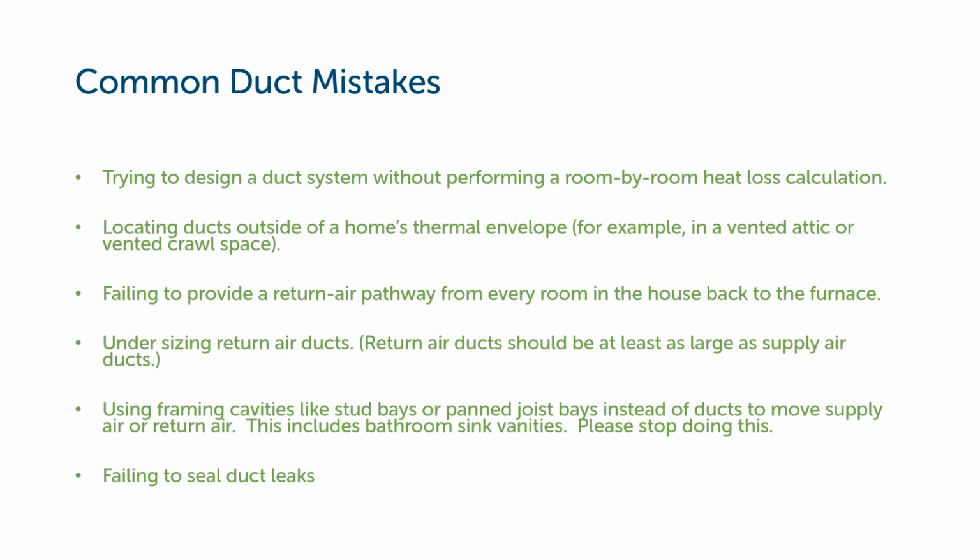Failing to provide a return air path for every room in the house. So being able to close off doors and not allowing return air to get back to the furnace. Undersizing the returns. Speaking of returns, those ducts should be at least as large as the supply ducts.